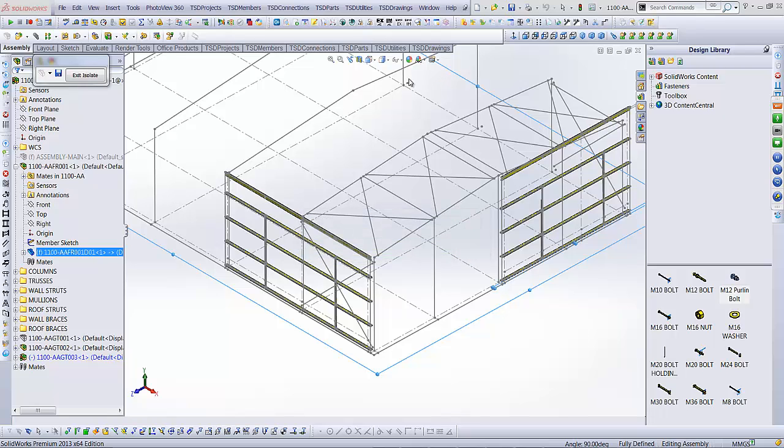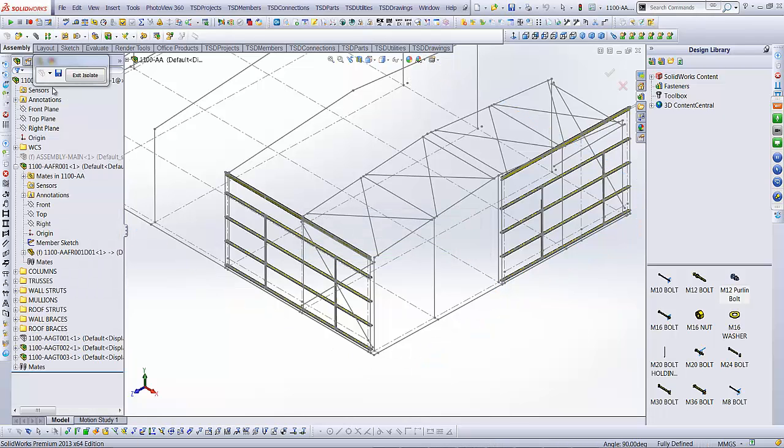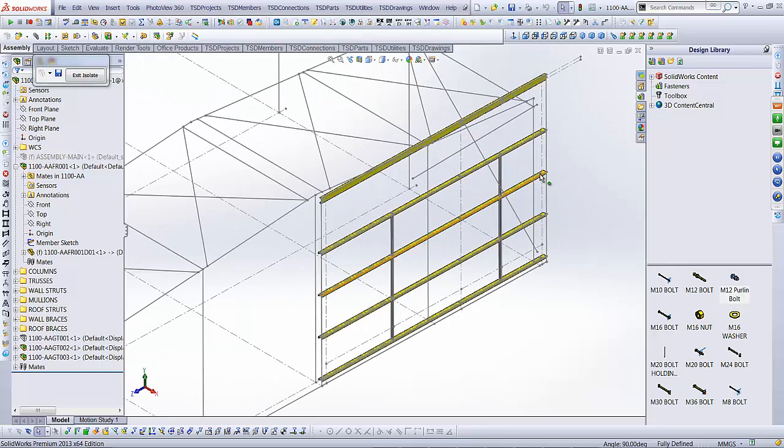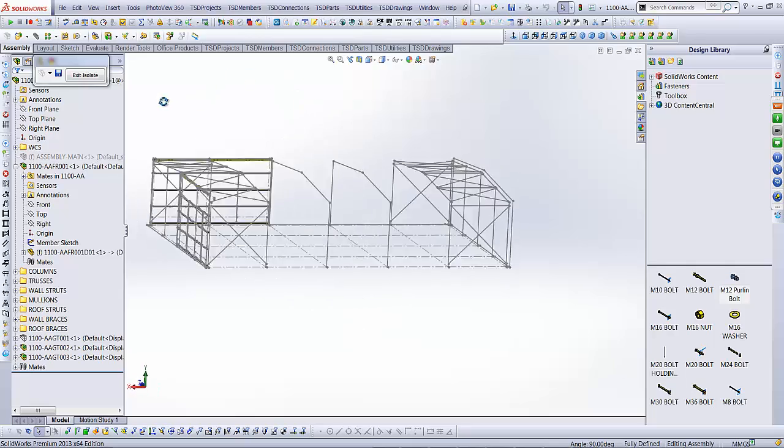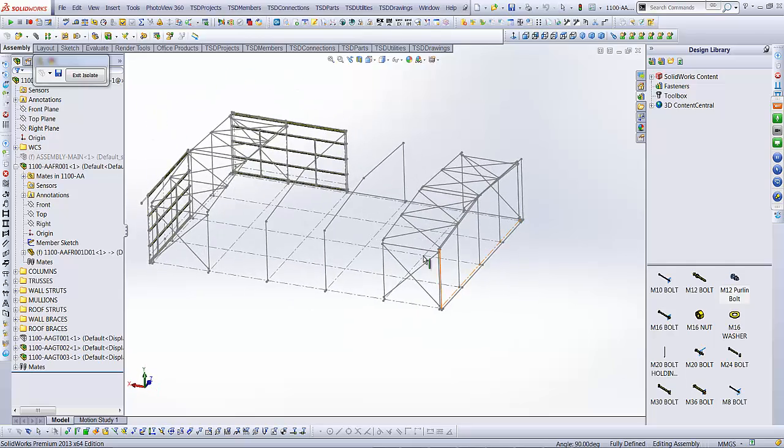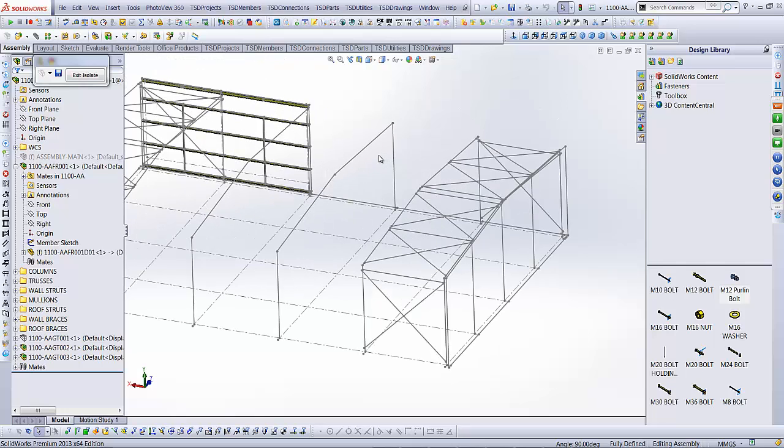And you'll notice that we have to do some snapping, because the girts themselves are hanging out over the edge of our frame, and we want to bring them in. And in this instance we don't need the fascia, so you just go and remove the fascia out of there, and you'll have to add another girt line in there, but the idea is to get 90% of the way there so that you can reuse them. Now I can come back and fiddle with that. That's just attaching sketches. Also, if I want to duplicate, so I've got this object over there and I want to bring it over here, I can do the same thing.